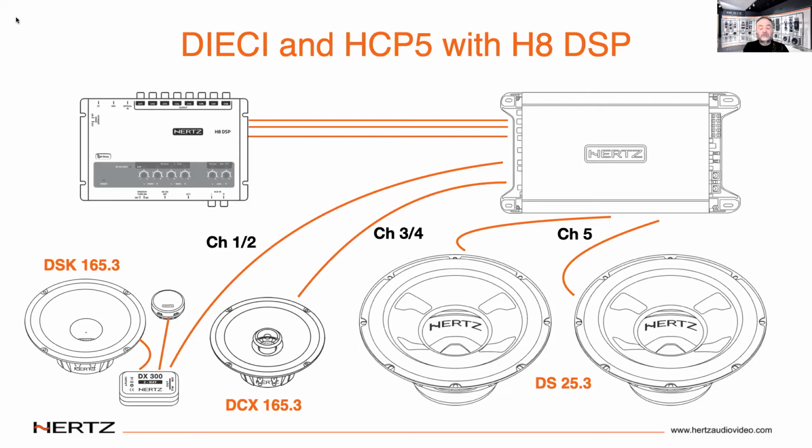Now, if this customer also wants a better stereo presentation, and those are my favorite customers, then we can make the left and the right sides match in level with the DSP, and we can make them match in response with the level and the EQ. And then we can make sure that the subwoofer is in phase with the door speakers, so the subwoofer sounds like it's up front with the rest of the band. So even with DHE, we get benefit from DSP, right?